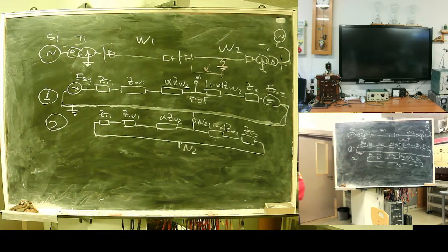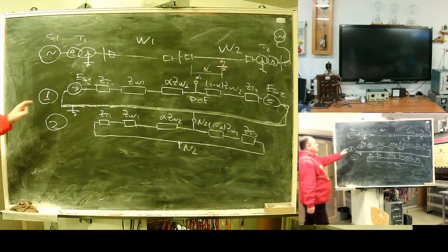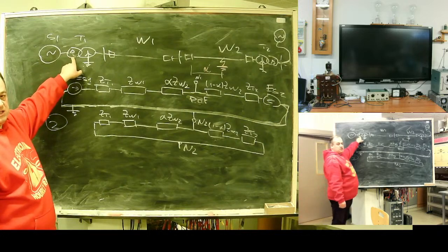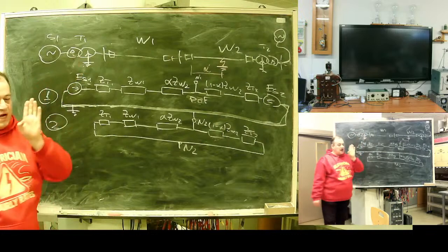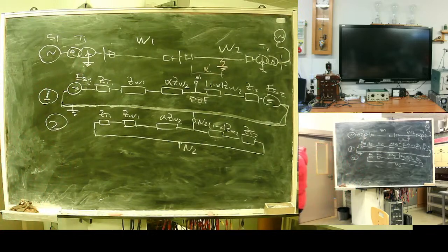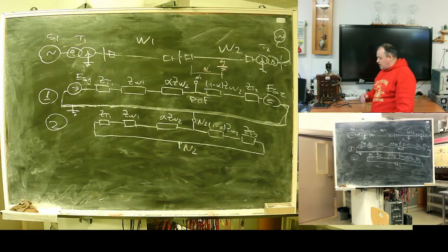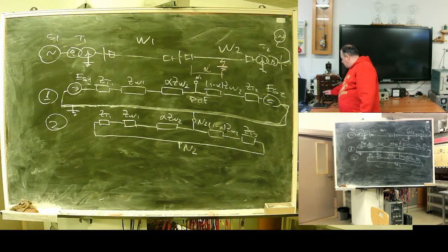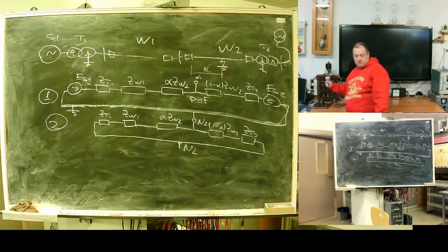And now, the important part. Since I have star delta transformers, try to understand this. In the zero sequence network, I should analyze the transformer as if all these terminals are connected together and the power source attached between the star center and these connected terminals.